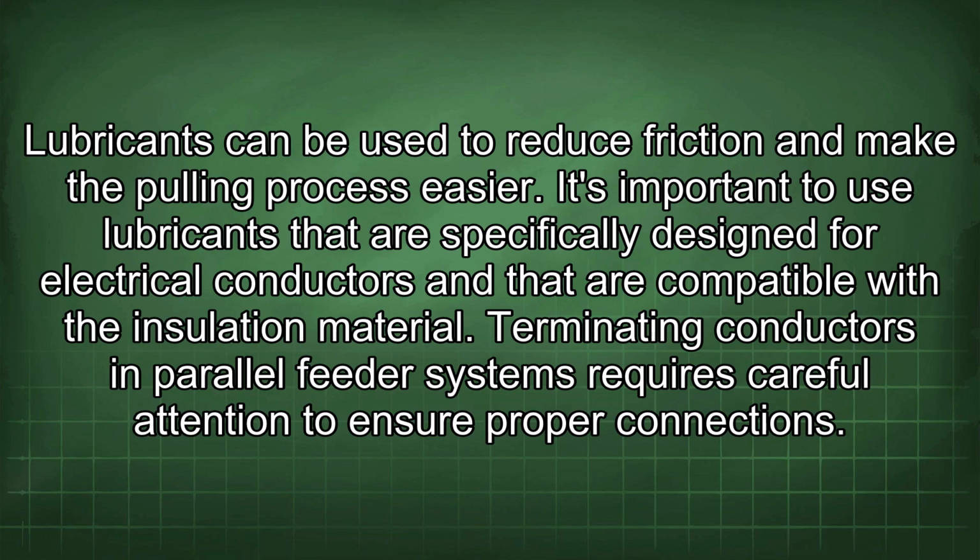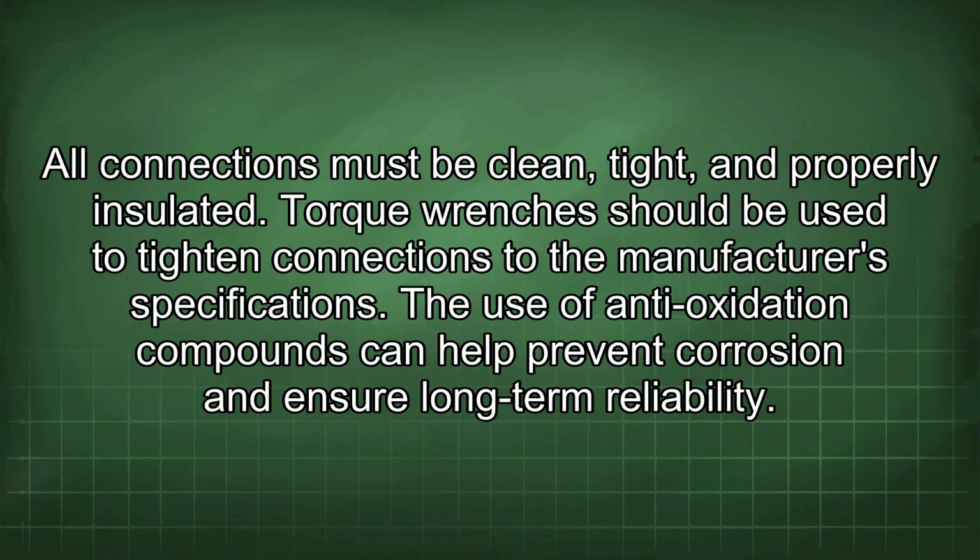Terminating conductors in parallel feeder systems requires careful attention to ensure proper connections. All connections must be clean, tight, and properly insulated. Torque wrenches should be used to tighten connections to the manufacturer's specifications. The use of anti-oxidation compounds can help prevent corrosion and ensure long-term reliability.